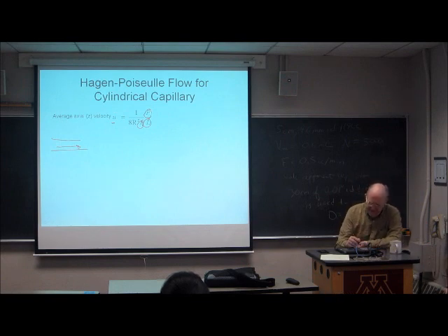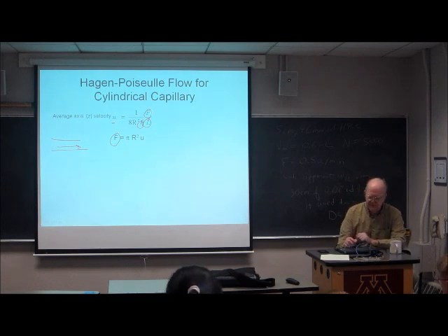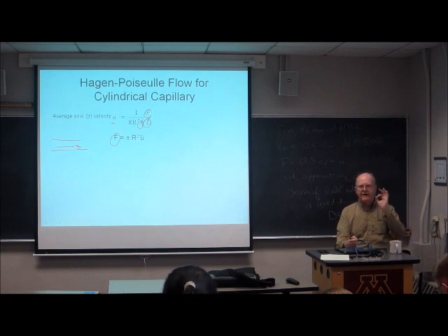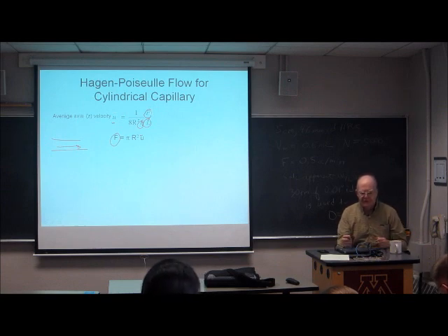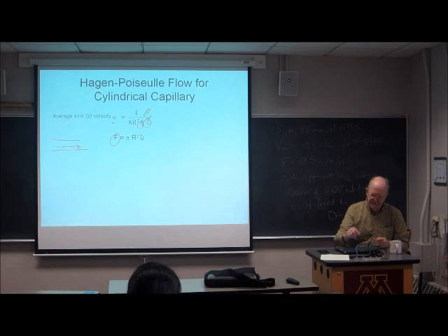However, I'll get to the however in a second. Your total flow, this is your volumetric flow now, U is your linear velocity. The total flow then would be equal to the average linear velocity, U bar, times the area of the tube. It's a circle, so it's pi r squared is this area. So your total flow is pi r squared times your average velocity. And you calculate the average velocity given the pressure from the Hagen-Poiseuille equation.